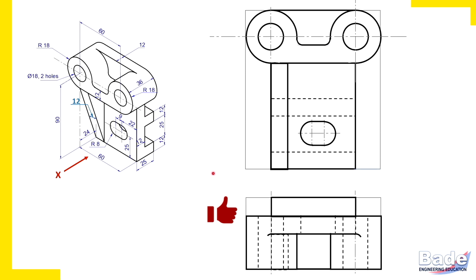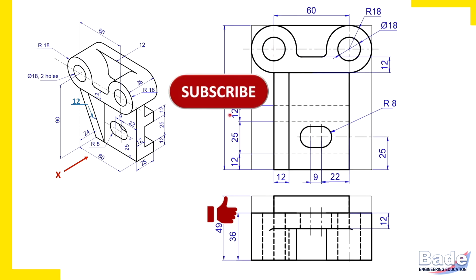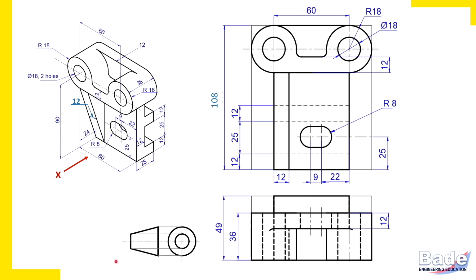Okay, let's proceed now. Insert all given dimensions, and which method of projection have we used here? First angle method of projection. Okay. Remember this again. In between the views, as far as possible, we don't insert dimensions. But as I have told you, the given dimensions must be nearer to the corresponding feature.